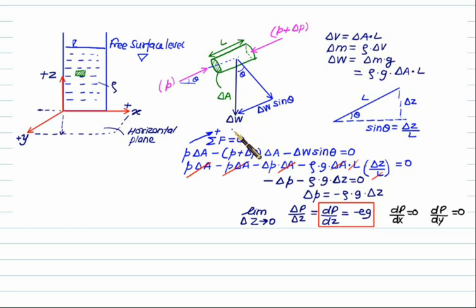The weight component is resolved into two parts: one is W sin theta and one is W cos theta. So this vertical component is W cos theta and this component is W sin theta. Since I have taken the element as the inclined axis, I will take this axis as the x axis and this axis as the y axis. I take this as the x axis because I have to resolve only one force. Therefore it is comfortable to align the x axis along the longitudinal axis.